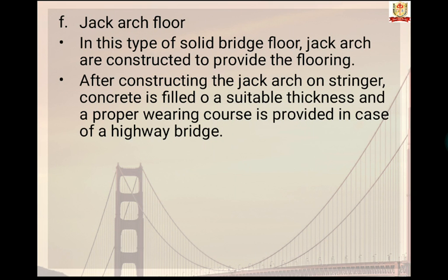Jack arch floors. In this type of solid bridge floor, jack arches are provided to construct the floor. After constructing the jack arch on stringers, concrete is filled to a suitable thickness and a proper wearing surface course is provided in the case of a highway bridge.